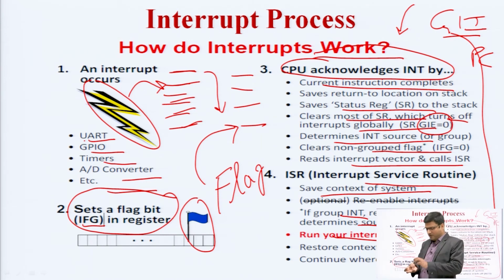The first point is that an interrupt can occur at any time. When the interrupt occurs, the processor will stop whatever it is doing, save the contents into the SR, the status register, and start servicing the interrupt. After the interrupt has been executed, the processor returns to the main program. These are the program steps.